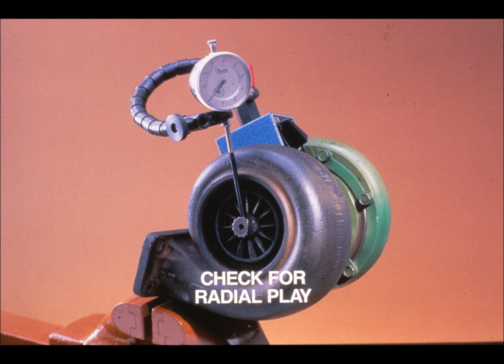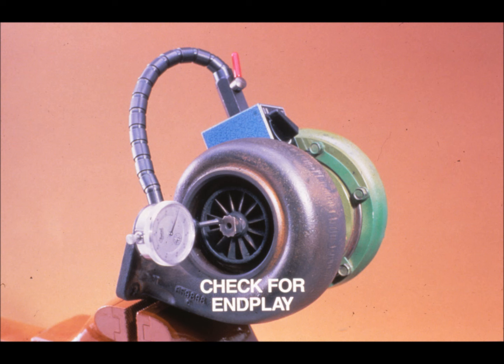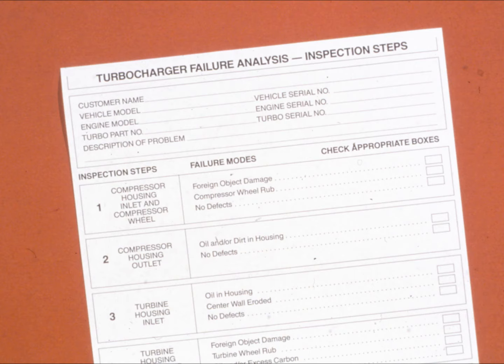The second phase of the diagnostic procedure involves checking bearing radial play and end play with a dial indicator. This procedure is not required if a failure mode has already been identified. These tests provide measured information on the condition of the turbocharger, which is then compared against established standards. Both of these tests are outlined in the appropriate technical manual. Proper specifications are also provided. These diagnostic procedures will allow you to determine the condition of the turbocharger.